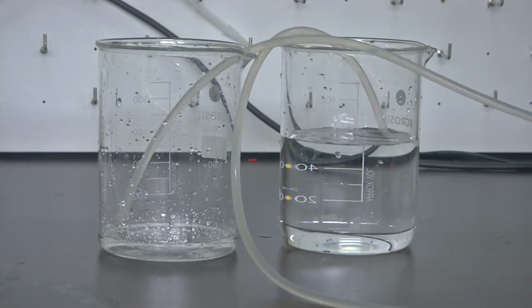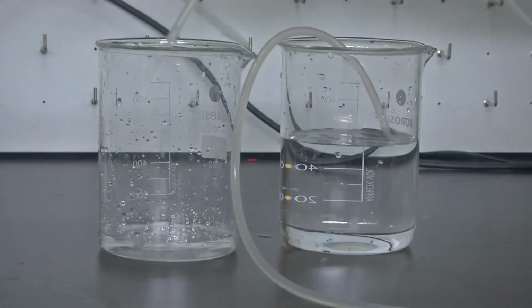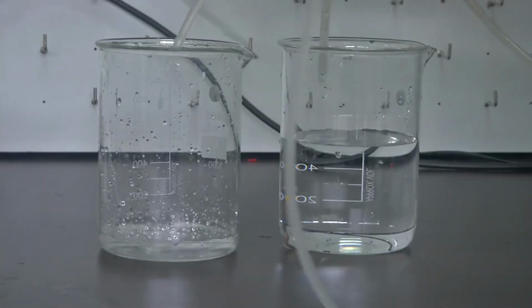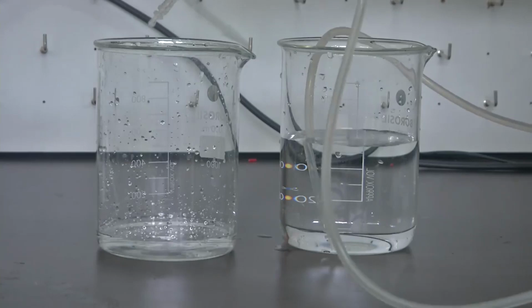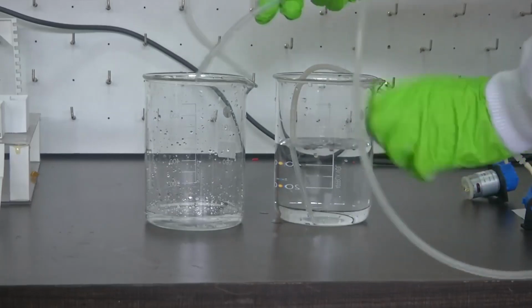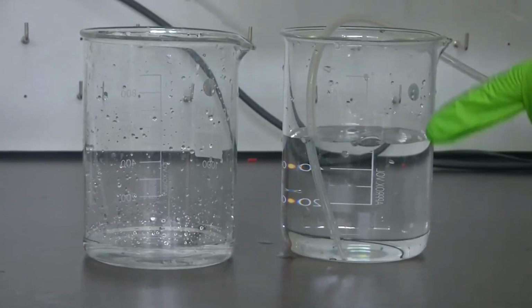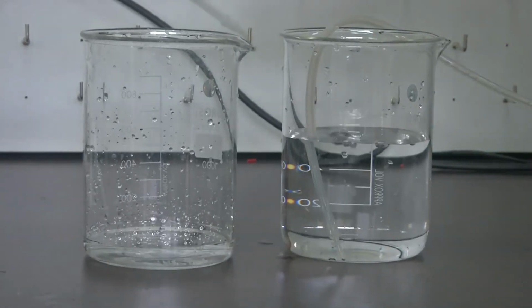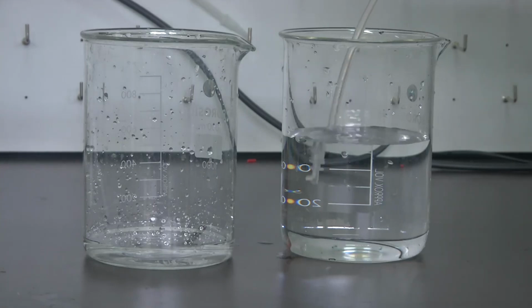You can see that the water level is increasing, right? And if I switch the cables now, you can see that water is no longer coming because the pump is pumping in the opposite direction. But you can see bubbles coming because now the air is being pumped. So the peristaltic pump can even pump air because it's a positive displacement pump. A centrifugal pump cannot do this. Since the peristaltic pump is positive displacement, it is self-priming.